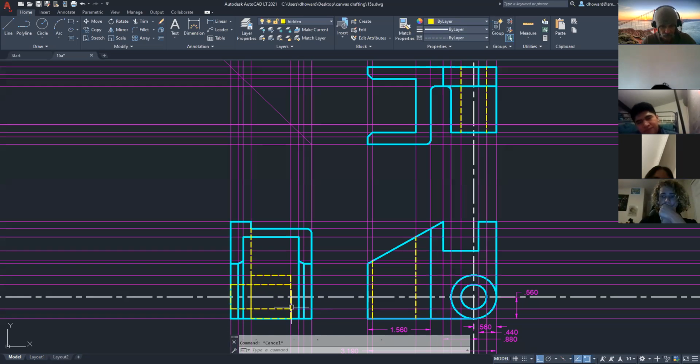That's the hole going through the whole thing. This is its outside edge. Of course, we don't put that little piece there. We also have the bottom of this notch to draw with a hidden line, so that would be from here to here.